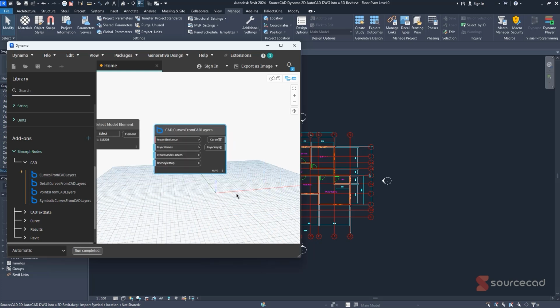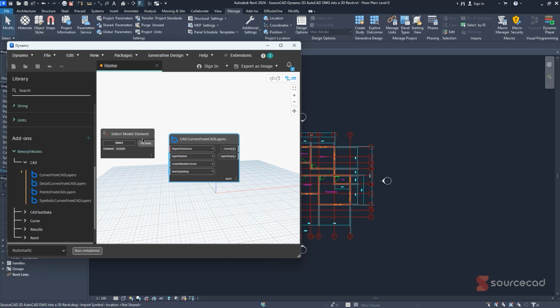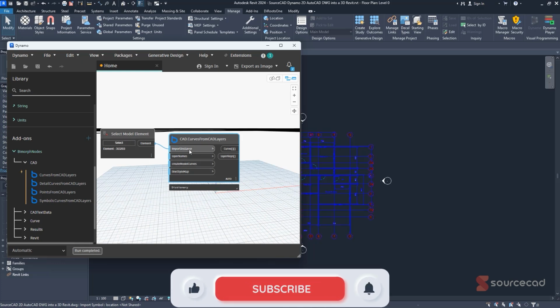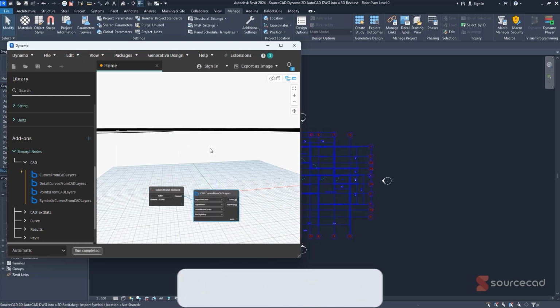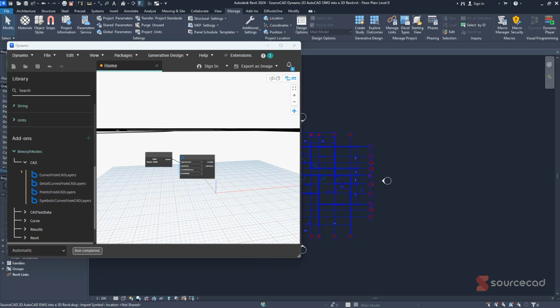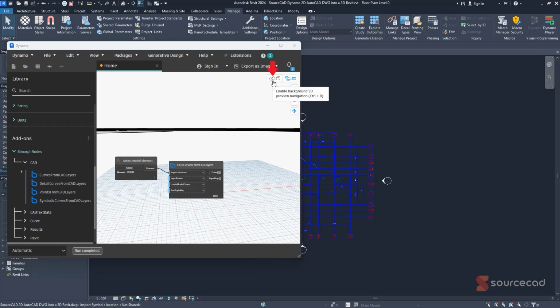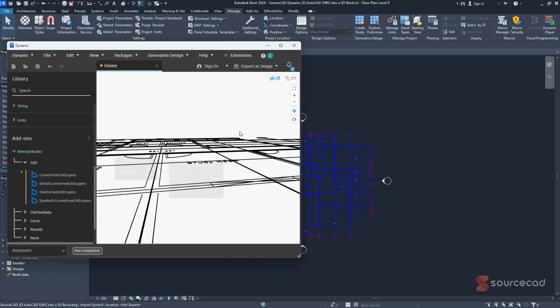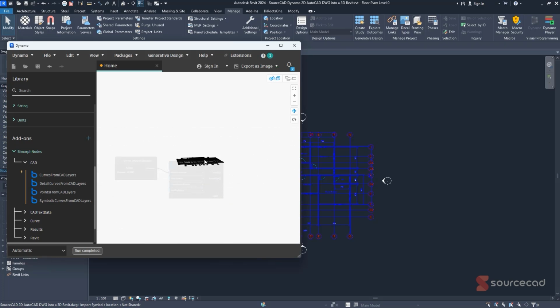So now let's create our string of connection between our script. So the element, we want to connect it to the import instance. So just click on element and then bring it now to the import instance. So you can either select to move your background, so you can click on this so that you don't see your preview, and we want to just zoom out so that we see this floor plan.